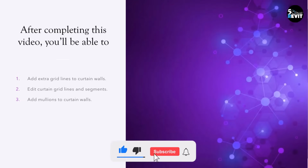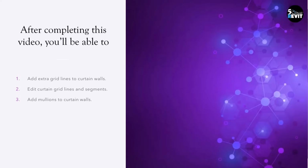In this video, we will see how to add grid lines to curtain walls using the Curtain Grids tool. We will also see how to edit grid lines to add and remove segments and merge panels together. And we will see how to add mullions to curtain walls using the Mullions tool.